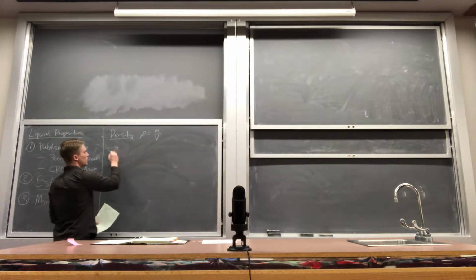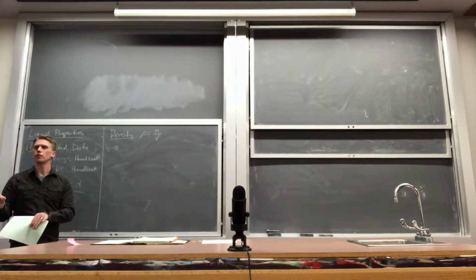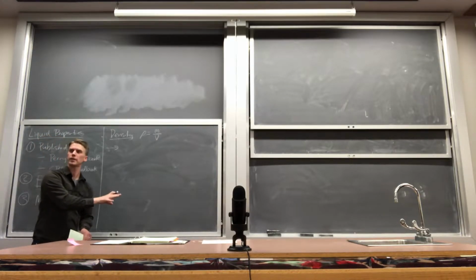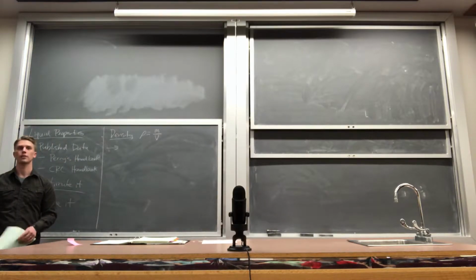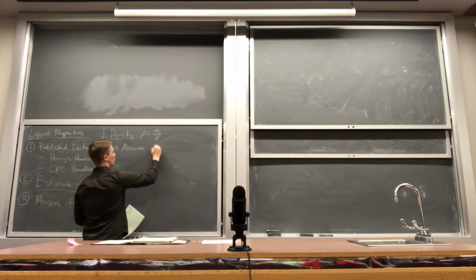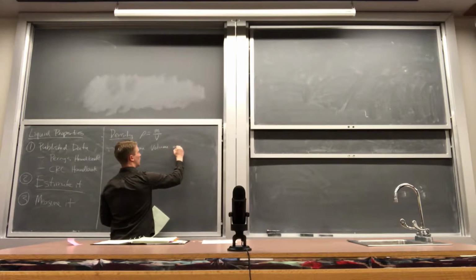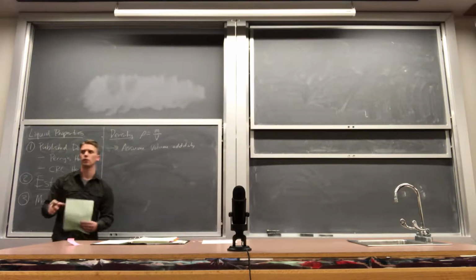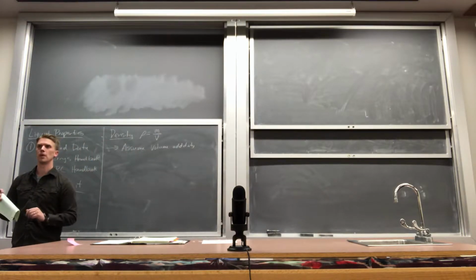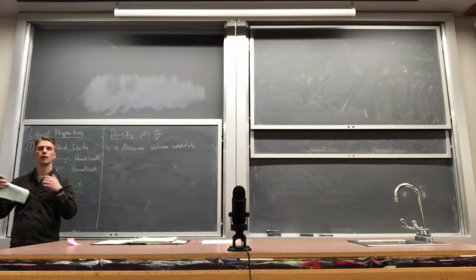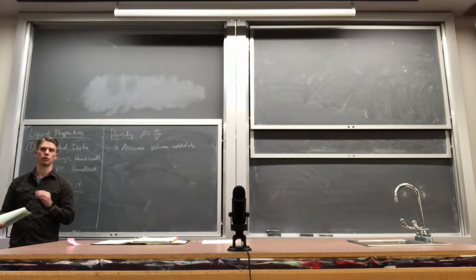Now, how we're going to calculate densities for fluid mixtures is we're going to do a very simplified assumption, which is going to be valid for this class, but it's not going to be valid for your Thermo 2 class. In Thermo 2, you're going to be talking about when this is not the case. But we're going to assume volume additivity. And this is generally only true for what they call ideal mixtures. So if I have 1 liter of fluid 1, 1 liter of fluid 2, I mix them together, I get 2 liters. In general, that's not actually true, right?